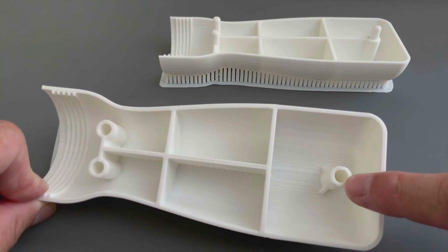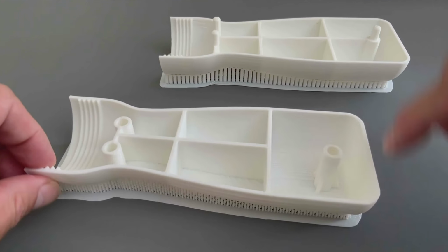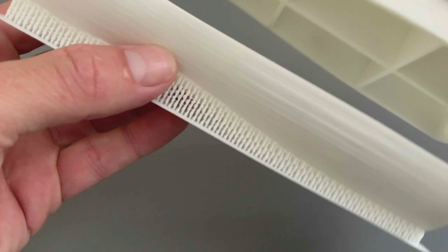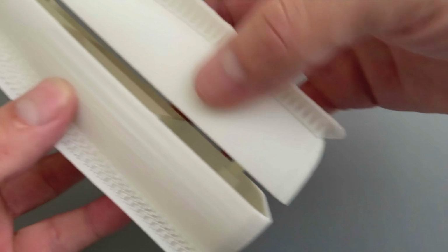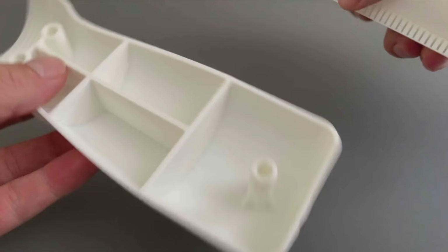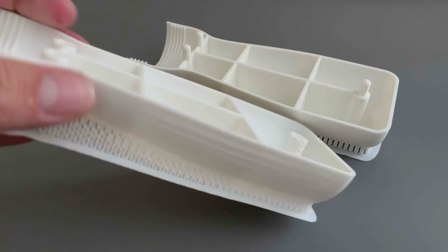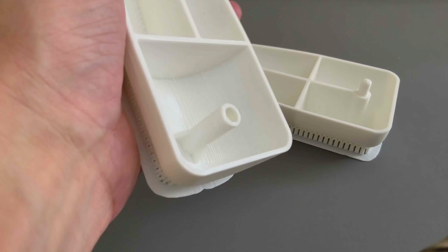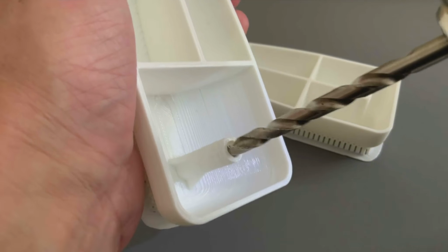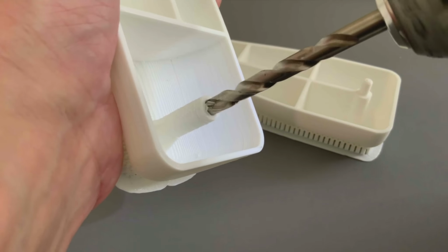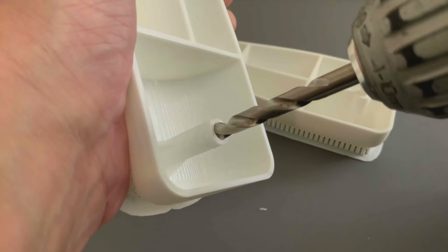So the wall thickness, the holes I did a little bit bigger because I wanted them to snap. Now you can also model everything if you want perfectly flush. In Shaper the pin is nearly exactly as wide as the cylinder, and then after the print is done you simply take a screwdriver and a drill, and then as you see here what I do, you just drill it clean.